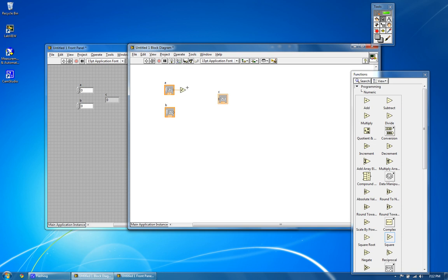On the block diagram, you have various things. You have your actual values, which are controls, which these correspond to. A is that one, B is that numeric control, and C, you notice these are on the right side, which means they are inputs. And then that is on the left side, which means it's an output. Any resulting operations you can send directly to C, but it has to be a numeric value. So we'll go ahead and drag two squares. These are called nodes.